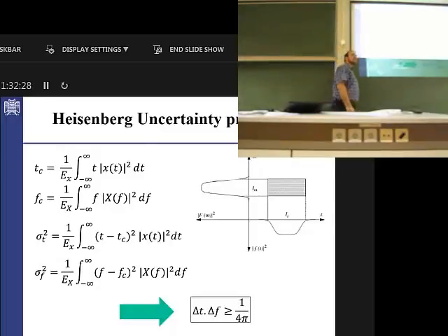And based on the Parseval theorem, the energy of the signal over the time is the same as the energy of the signal over the frequencies. You will never lose the energy or the information of the signal by just transforming from one domain to another. Okay? Energy is fixed. You're just changing your eyeglasses. How to look at the signal is different.